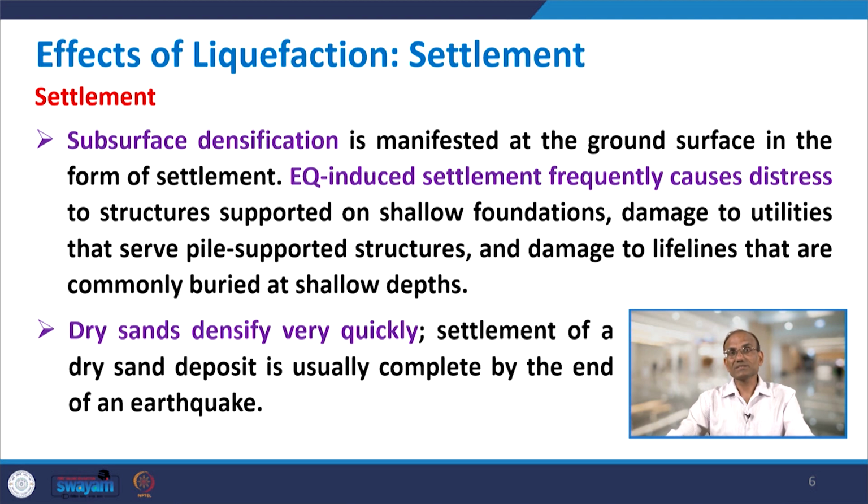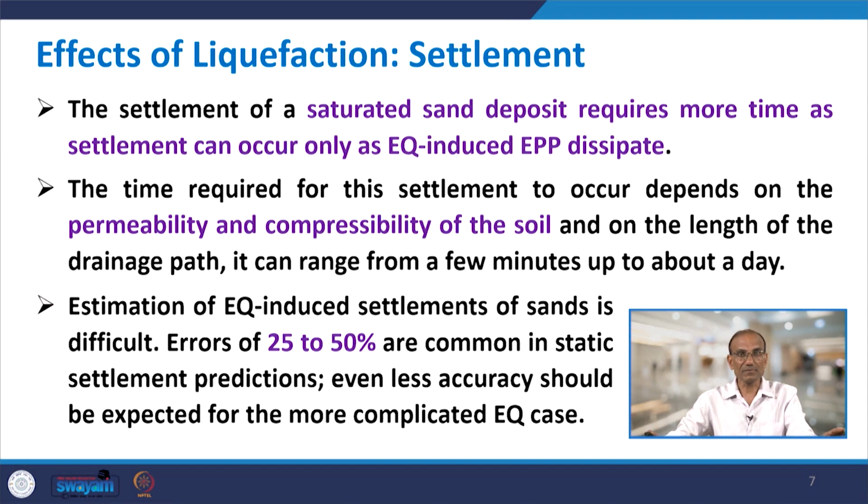Dry sand deposits will densify very quickly, because in dry sand you have air inside the voids, and when you apply loading there will be compaction, and compaction is a faster process than consolidation, as you may be aware. So, the settlement of a dry sand deposit is usually complete by the end of an earthquake. The earthquake time history lasts for about a minute or so, and when the earthquake ends, this settlement will be completed.